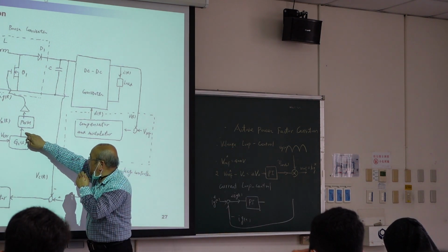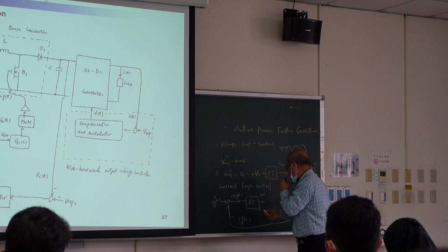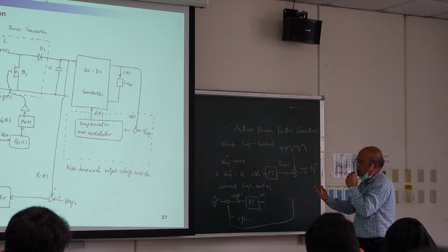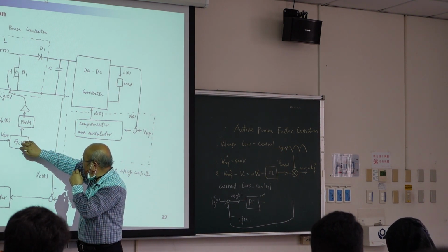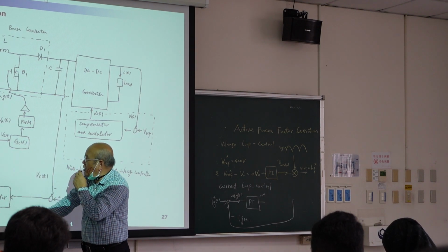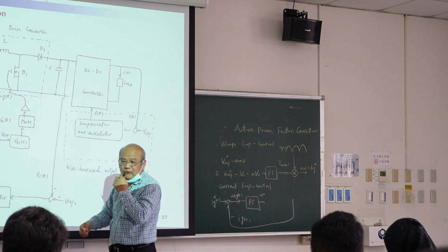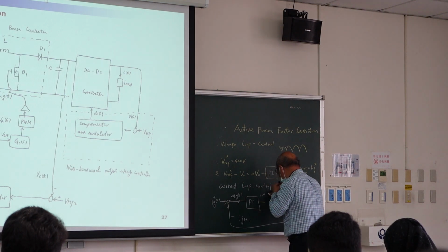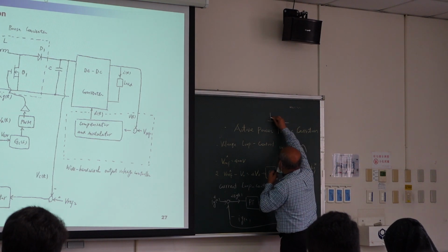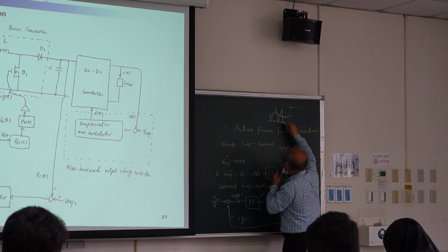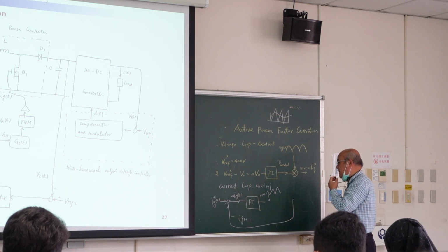And we can generate the control signal. So this is control U for current. But the control U should change to switching. So how can we change a linear value control to on-off control? You have to use what? PWM, right? We mentioned before. So then you have to compare the control signal with the PWM signal. So we have control signal here. We have PWM signal here, right? We can determine on and off. So we mentioned this before.